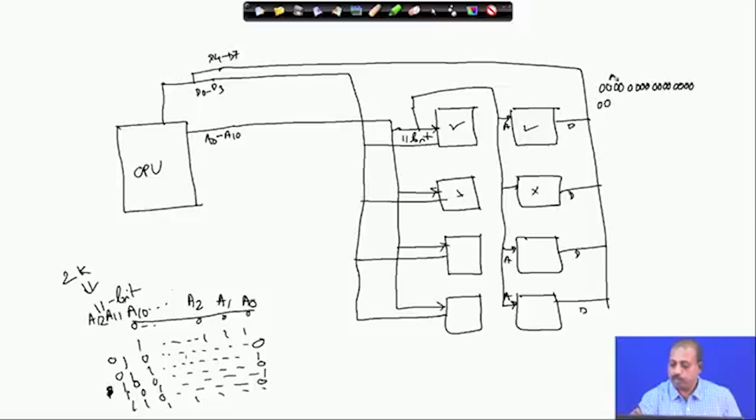I am interested in the bits A11 and A12. So, this is bit 15, 14, 13, 12, so this bit and this bit. These two bits I am interested in: this is A12, this is A11. From 0000 up to 1111, the first bank should be selected.